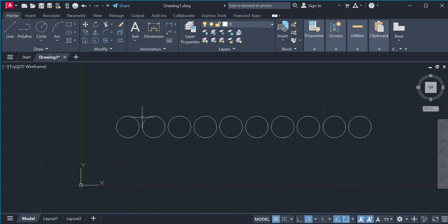In this video, we will be tackling layers, essentially how you can specify a new layer, turn it on and off, freeze or thaw, lock and unlock, and how you can make sure that your work is visible once you print your work. From the home page, on your ribbon, you're able to access your layers on here.